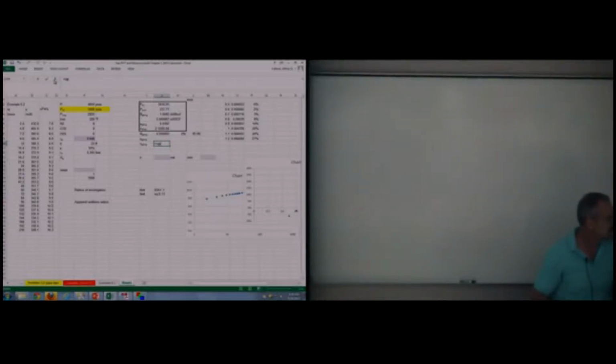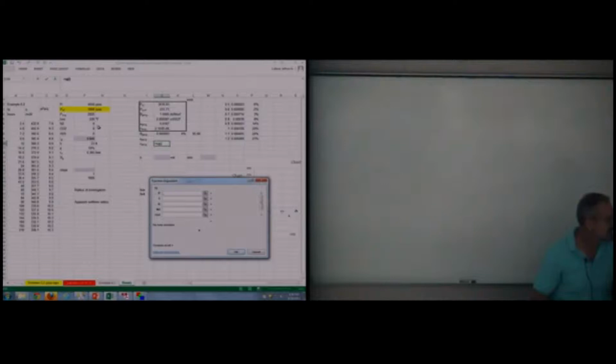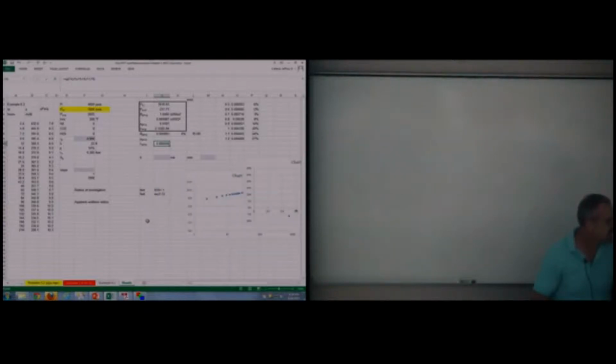You need average pressure, temperature, this new gas gravity that we solved for, and impurities. Don't forget to get that last one or you'll get a wrong value. And then my gas saturation should be equal to their given CT divided by my CG. And I got a reasonable value.